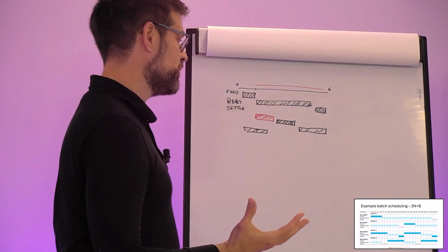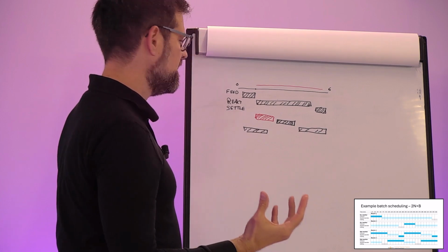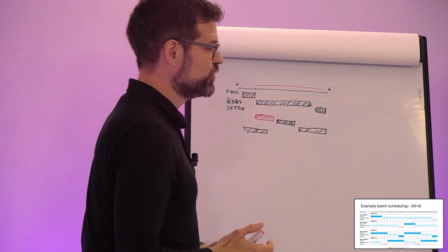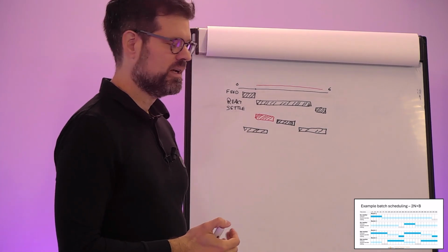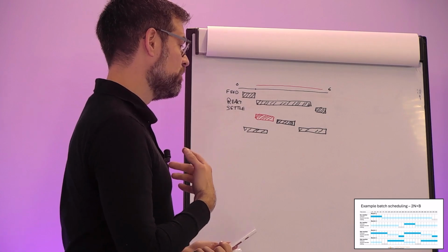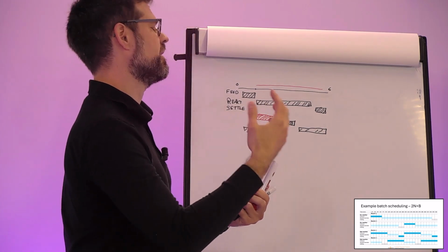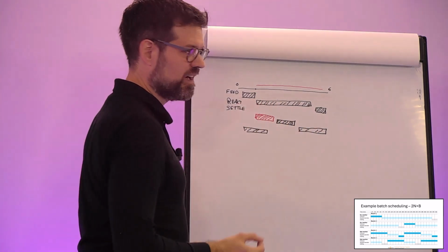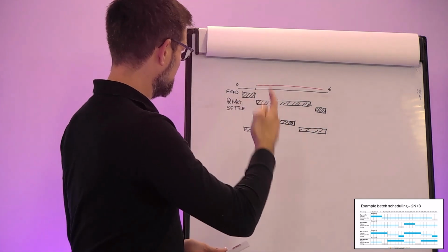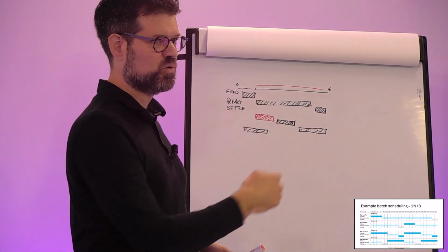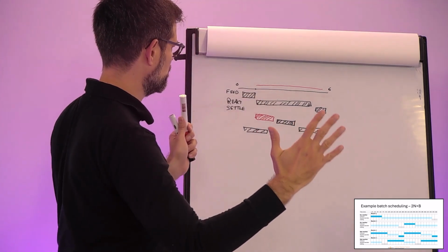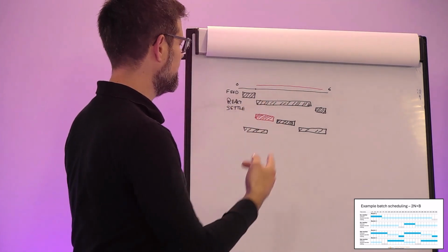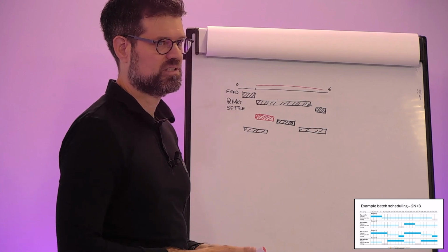In most wastewater treatment plants, we also have rain weather conditions. And then the flow might double, triple, be 10 times as high as during dry weather flow. And then suddenly you have to treat much more flow, most of the time basically with the same load. And then you have to squeeze in those cycles because you have to run much more water. So the feeding phase has to continue faster. And most of the time you then shorten the total cycle time, and you are more feeding and less reacting in the rain weather conditions.